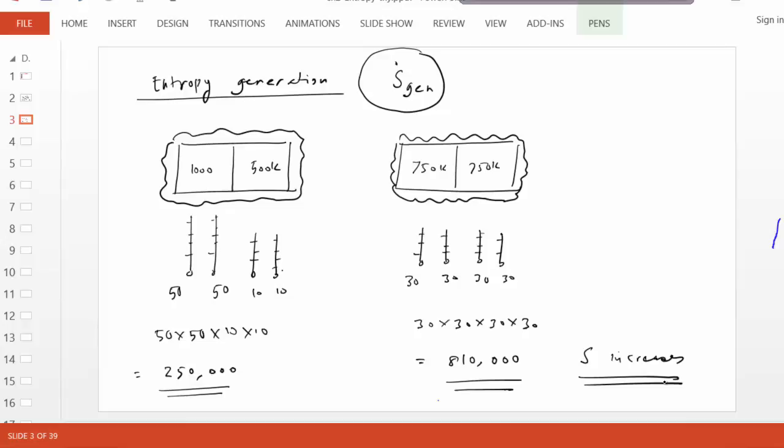How can we remember this? A simple way to remember this is to just think about friction. As mechanical engineers, we understand friction really well. And friction in thermodynamics should mean that it is trying to destroy a velocity gradient. Likewise here, some phenomenon is destroying the temperature difference, and that's called heat transfer. So it can be thought of as thermal friction that is destroying the temperature difference. Similarly, we can think of chemical friction when there's a chemical reaction. All of these will generate entropy. And to generalize that, we call that thermodynamic friction.